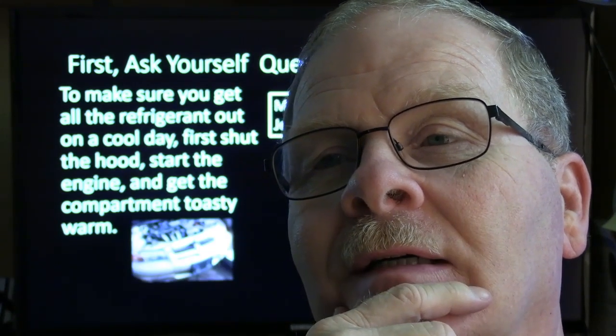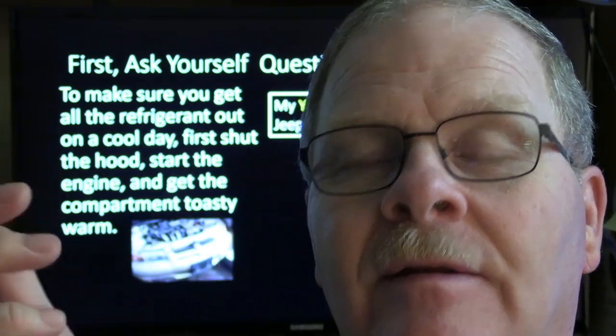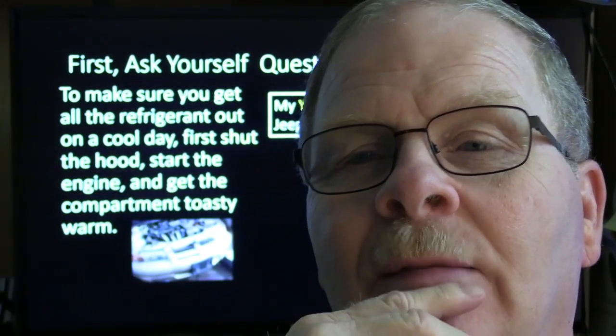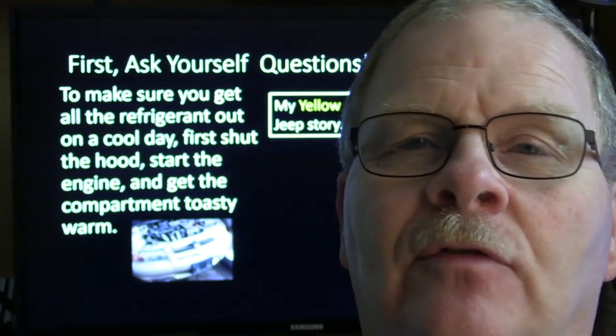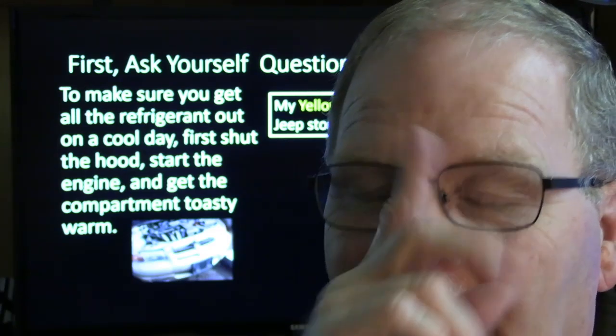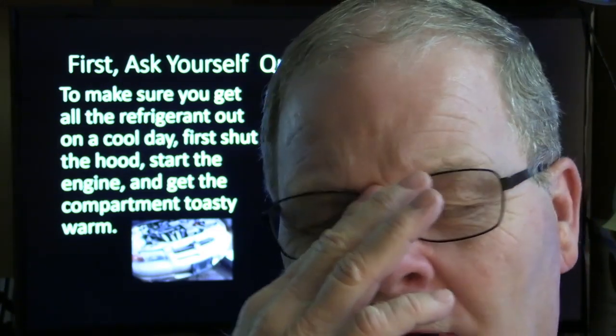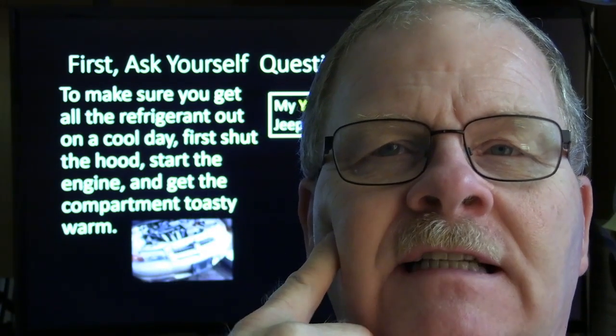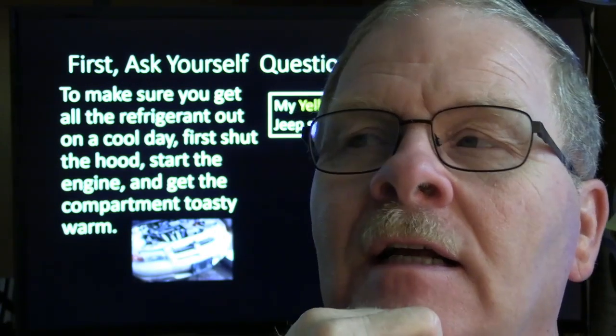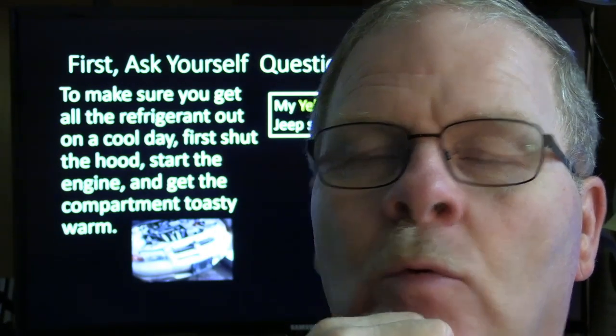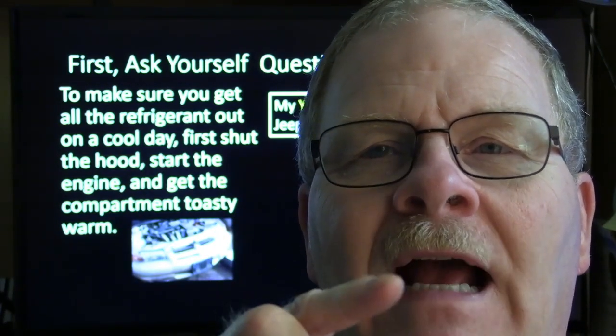And so I let it pull the refrigerant out, and both gauges went into the negative, and it told me that it had pulled out 1.2 pounds of refrigerant. Well, it held 1.25, and so whatever happened, the phone rang or something. I went back in my office and I stayed in there talking on the phone and doing some other work. I was there by myself that day for probably 25 minutes. And when I went back out there, that refrigerant had outgassed.